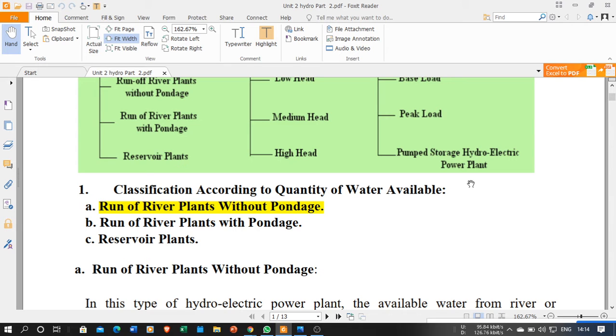That water flows through the turbine. The turbine rotates, and it is connected to the alternator. The alternator rotates and generates the electricity, and that water is stored in the lower reservoir. Now, during the night or when the load on the system is less, I use the electricity from the grid to rotate the alternator as a motor and the turbine as a pump. Remember, during off-peak hours, when the electricity demand in my system is less, in a pump storage power plant we use the alternator as a motor and the turbine as a pump to lift the water from the lower reservoir to the upper reservoir.